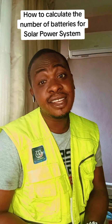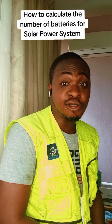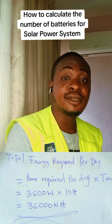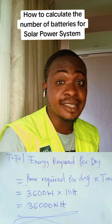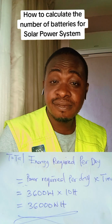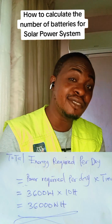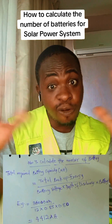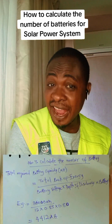Let's assume that your load is around 3,600 watts, and you want to run it for 10 hours. So it's going to be 3,600 watts times 10, and that is going to give you 36,000 watt hours. That is the energy you require for the total battery capacity, the whole battery you need for the day, equals the total backup energy.